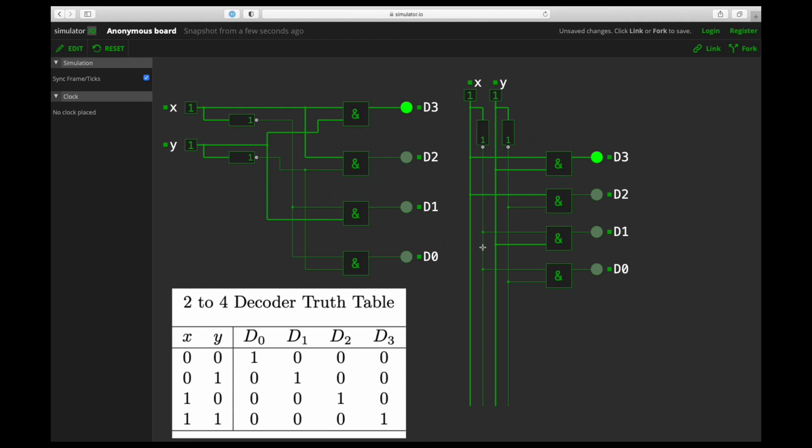And if you follow the traces correctly between the left circuit and the right circuit, you will see that they're indeed completely identical, as you can see that they implement the same truth table. But you also see that the structure on the right-hand side is much, much easier to understand and easier to see, because you can directly reconstruct the truth table from the circuit and vice versa. And whenever you typically see circuit diagrams for control units for CPUs, this is what they're going to look like.